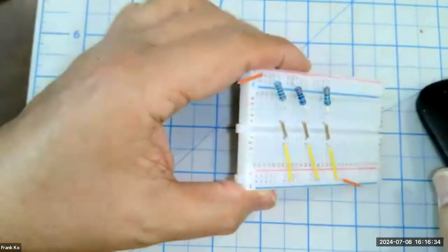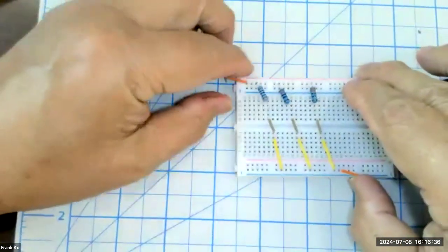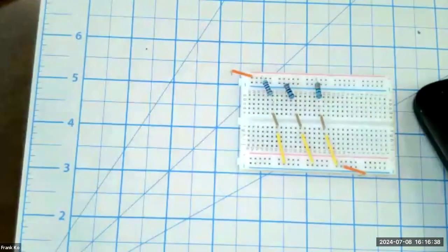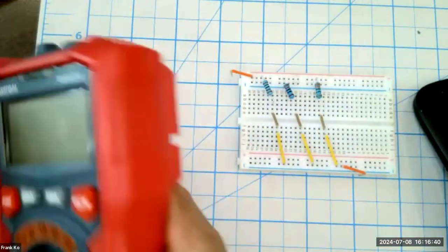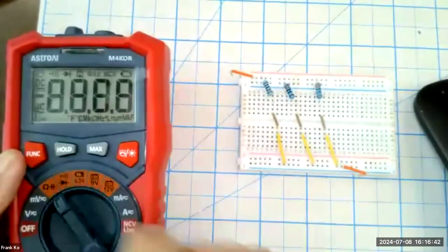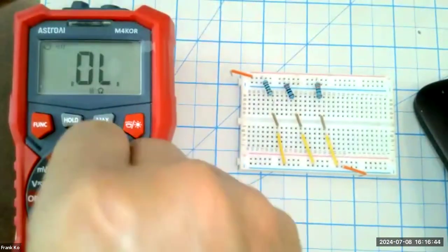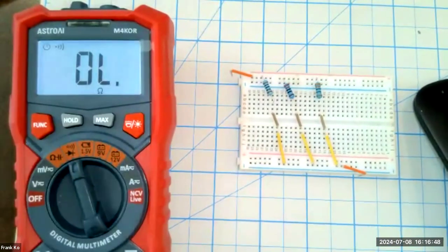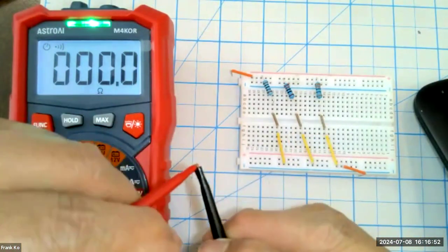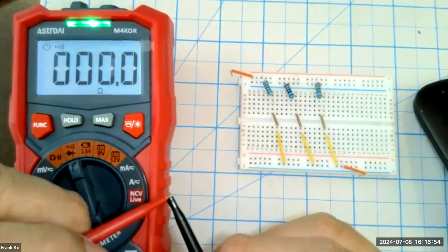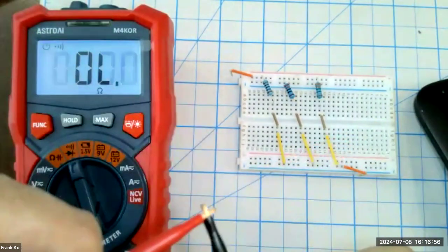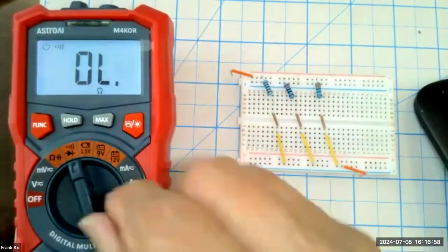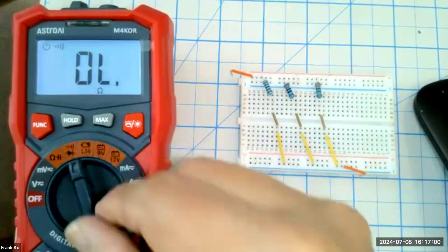So we hope to measure, and I'll bring in the multimeter, and here we go. Set this to read omega. And again, it never hurts to double check your continuity. So you take your two leads, yes, it beeps, it goes to 0. You might hear the tone. You may or may not hear the tone. The microphone may have a challenge at that frequency.